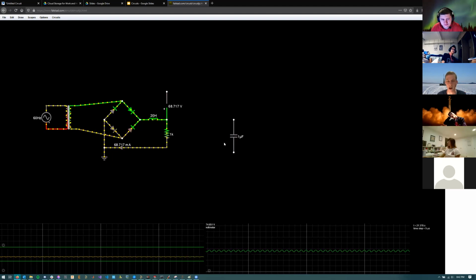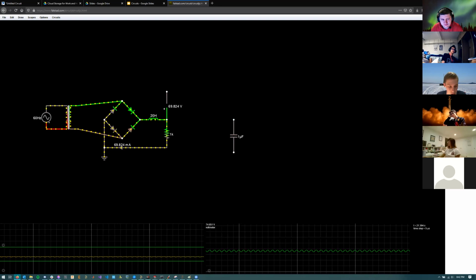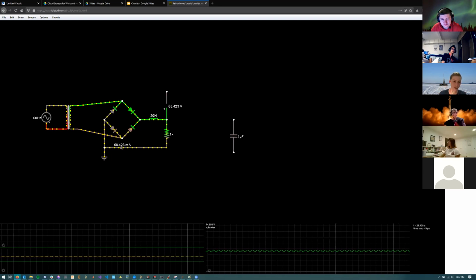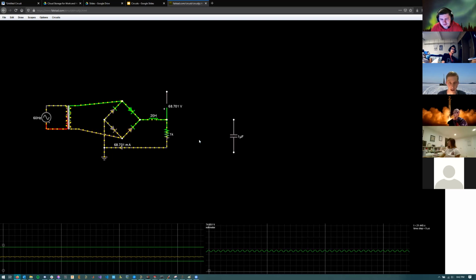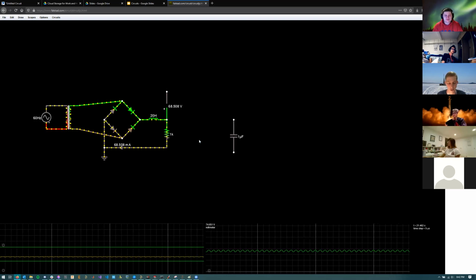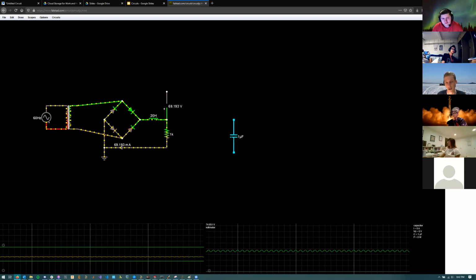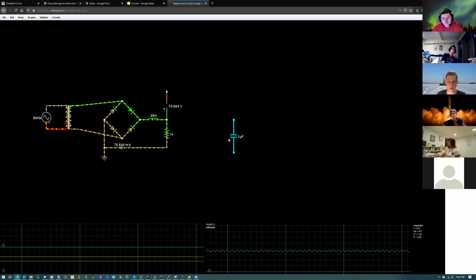I forget why exactly that is, but essentially you can't use a tiny little capacitor for a huge voltage. You have to increase the size. So if you look at a 1,000-volt capacitor that's 1 microfarad, it'll be huge compared to a 10-volt 1 microfarad capacitor.